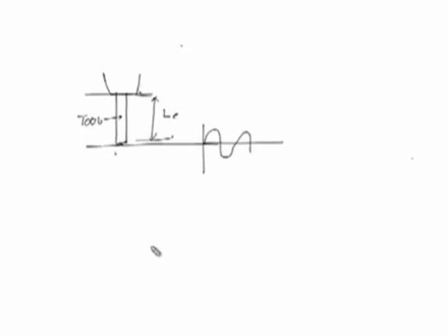Now, in due course of time, because of the striking abrasive particles, the tool tip gets shortened like this. In fact, it will be rounded as well because of the continuous striking of the abrasives, and the tool length becomes, say, LE1, where LE1 is less than LE. So, this is the used tool.